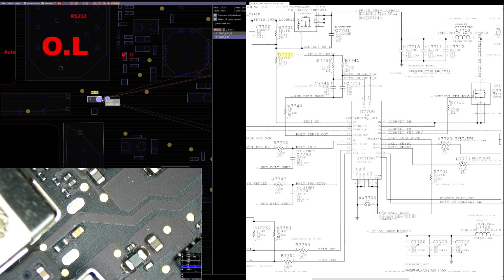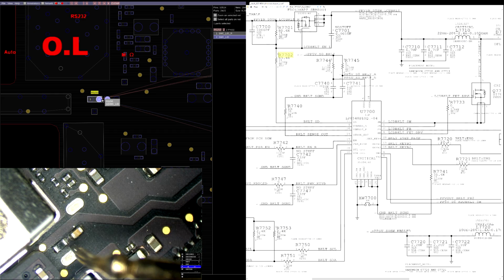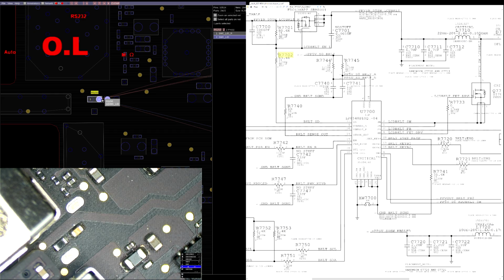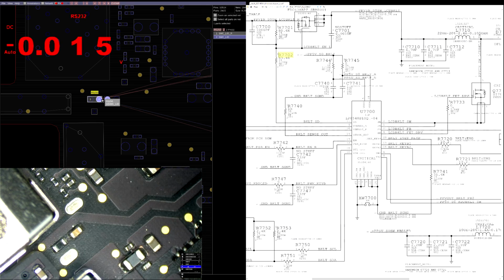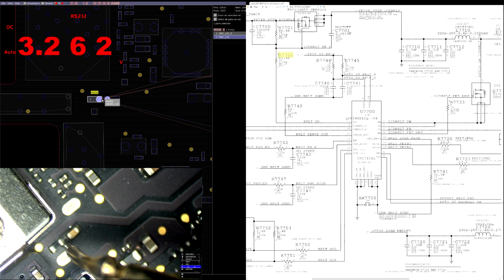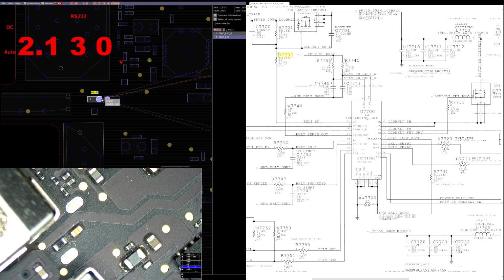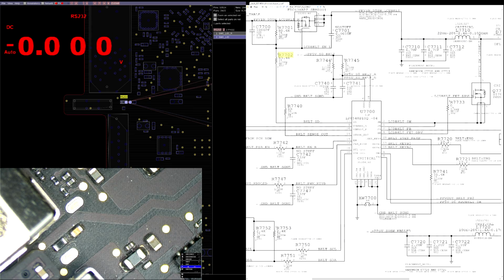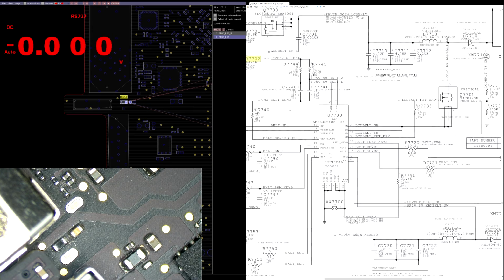Okay, we're turning it on. SMC lid should be 3.4 volts. If not, it's going to think that it's closed. And we're going to put it in voltage mode. And it's 3.39, which means the computer does not think it's closed, so it thinks that the computer's open. Which means we...